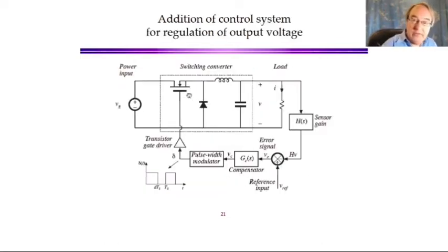Here's one way to realize the switch using transistors and diodes. We have a power MOSFET and a power diode that switch together. And I've also shown here a feedback circuit, say a simple analog feedback circuit, that adjusts the duty cycle. It actually turns the transistor on and off and adjusts its duty cycle to regulate the output voltage. So this is a buck regulator.